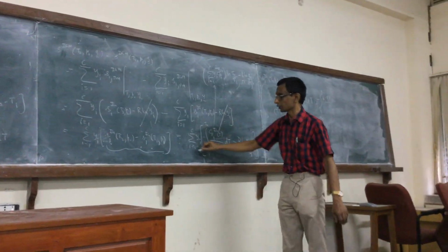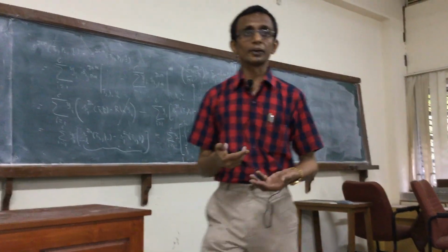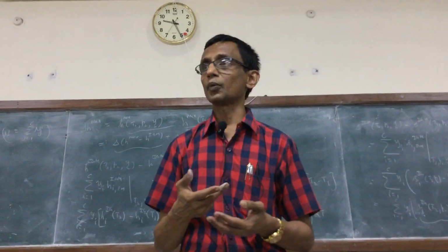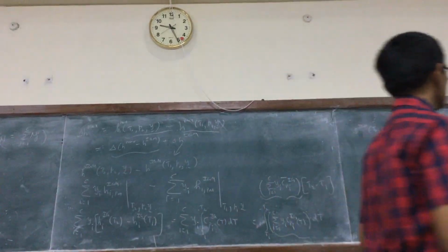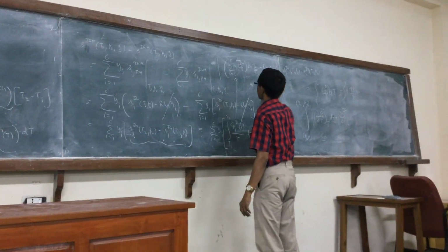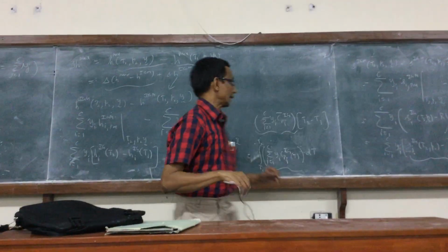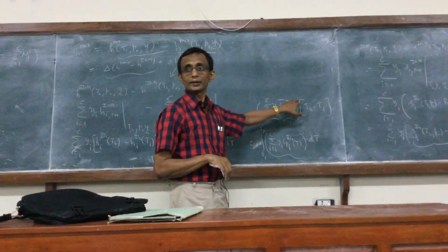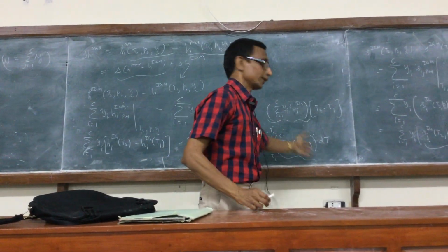Because the other one should simply be the sum over i equal to 1 to c of y_i multiplying minus R log P2 by P1. So that adds up to 1. The sum of all the mole fractions is 1. Right? So this is what we get for the entropy. You can easily calculate what it will be for the internal energy. You can easily guess that it's going to be replaced by Cv_i times T2 minus T1 for a constant specific heat. Otherwise, you have to integrate Cv_i.